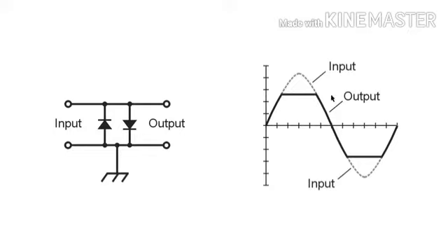You can clip that like this to about 5 or 6 tenths of a volt, and depending upon the impedance of your headset or your audio output, that may occur at a rather loud level of volume, or it may occur at a very faint level of volume. The higher the impedance, the fainter the volume level at which this clipping will occur. But in practice, it turned out to work pretty well with ordinary headphones. And so in the olden days, when you were listening to Morse code in particular on a radio, and a strong signal would come in, you could prevent it from blasting you.